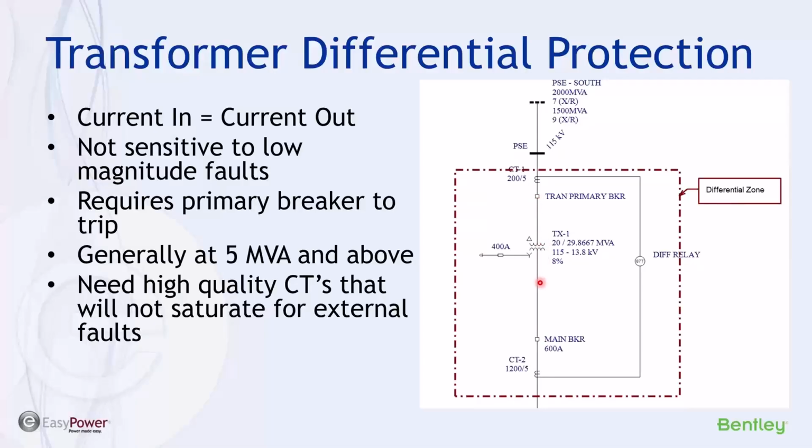And as we discussed in other webinars or discussions about coordination, this zone can be extended by placing the CTs lower in the distribution system, and that can determine better coverage on the higher current elements.